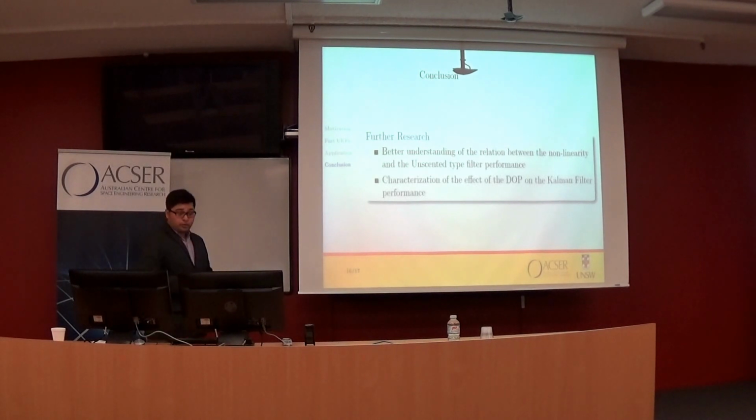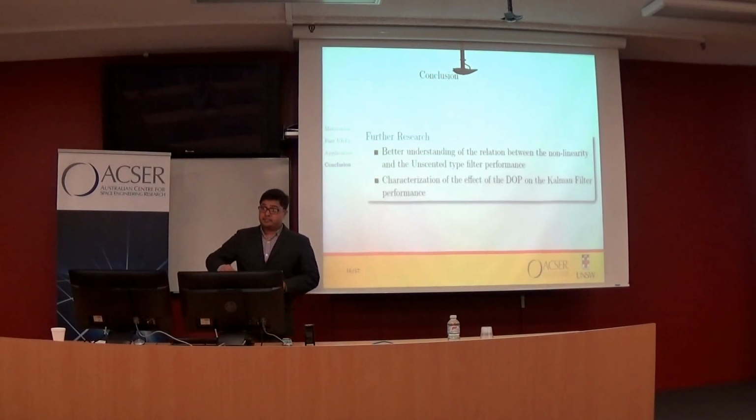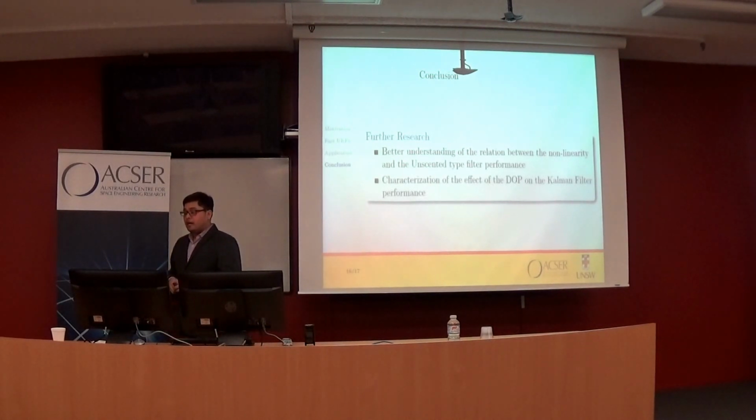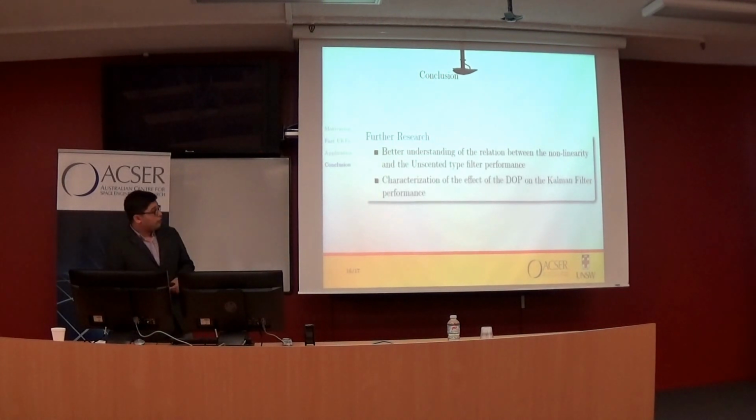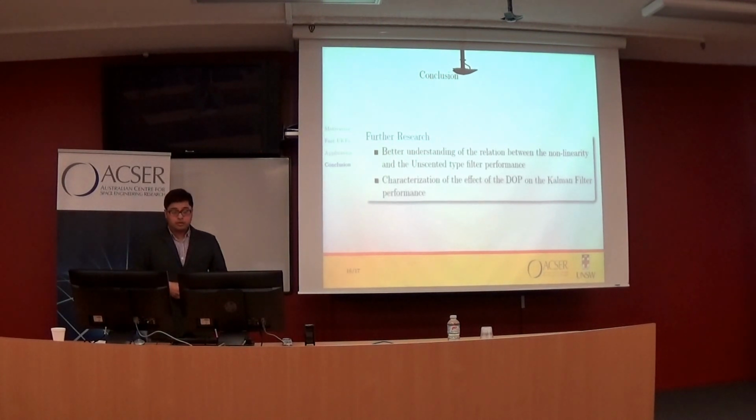And then, I showed an interesting observation that the error ratio, the error divided by PDOP multiplied by sigma r, varies for Kalman filters, but for least squares it should not vary. For the Kalman filter there is a hyperbolic relationship between the standard deviation of the Kalman filter and the DOP. That's why this variation happens.